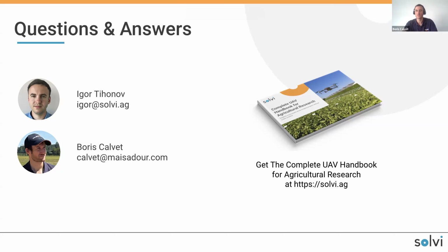I was expecting maybe it would have some problems of connection between the drone and RTK, and so far it works really well. And I'm sure that's because all the farmers are using that in their tractors, so it's a technology that is really mature. And my experience with PPK was not with a drone, but was not so good. So I would recommend if you have the possibility to use RTK whenever possible.